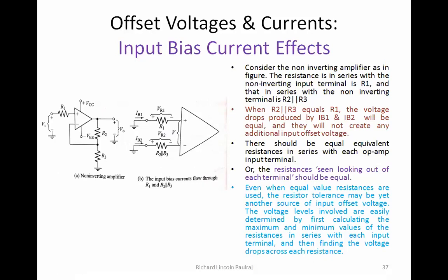There is going to be a voltage difference. Now, if there is a voltage difference, are we going to get zero voltage at the output, students? When are we going to get zero voltage at the output? Only when there is no potential difference. Both the potentials, at the non-inverting terminal and at the inverting terminal, should be the same.